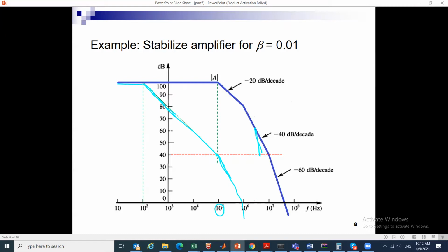Okay, so at minus 20 dB with a single pole, the first pole gave me a contribution of 45 degrees, and the second pole already gave me minus 90, pardon me. The first pole, maybe I said it wrong in the beginning of the lecture. If I have 10 folds or more, as in this example, how much did the first pole give me? Here we crossed 10 folds, right?